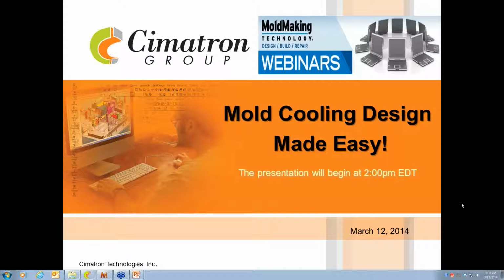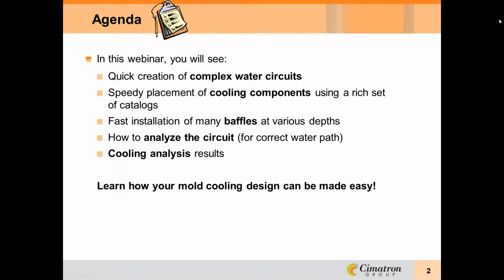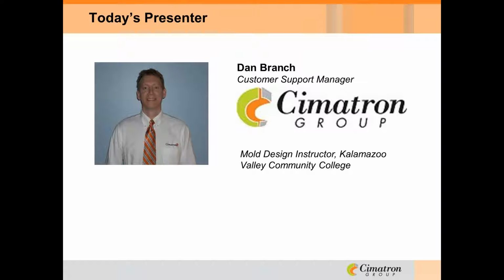Our topic this afternoon is mold cooling design made easy. During this webinar, you will see quick creation of complex water circuits, speedy placement of cooling components using a rich set of catalogs, fast installation of many baffles of various depths, how to analyze the circuit for correct water path, and cooling analysis results.